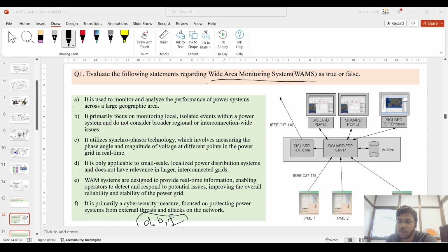Dharni is asking one question: does the C rate of the battery affect SOH? Yes, that will affect SOH. If you have a higher C rate, it means that you are charging and forcing the lithium ions to intercalate inside the battery cell.